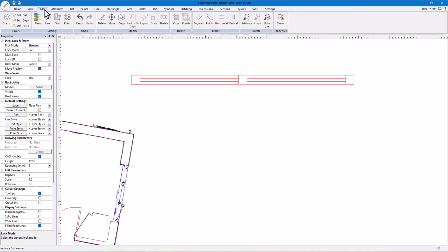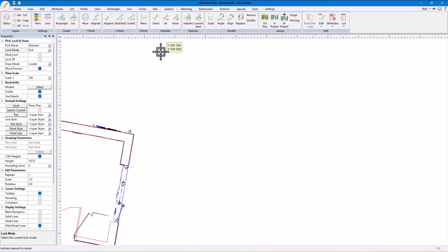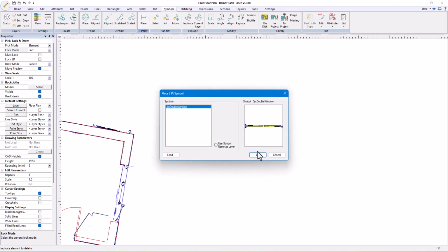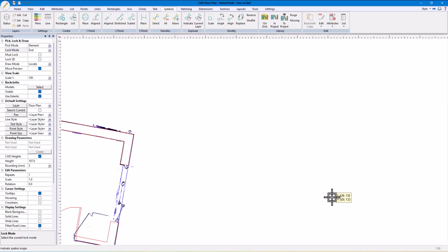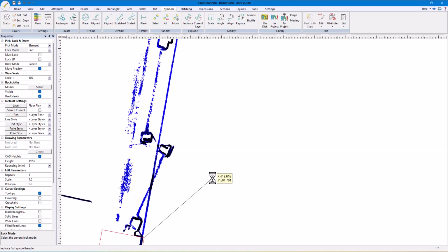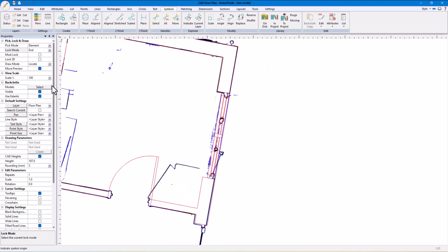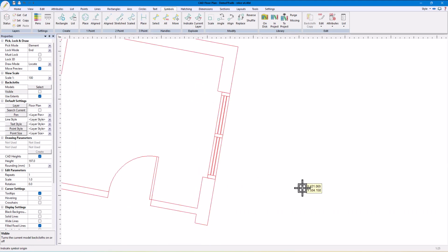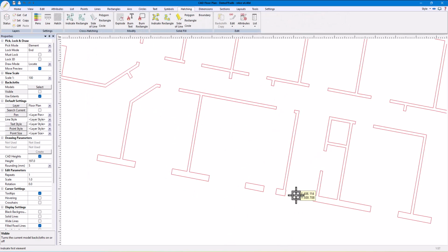Now we can delete the symbol and try to reinsert it using the 3-point option to test it. That seems to work fine, so we can fit it into an appropriate opening. Note, the end lock mode has no effect if there is nothing suitable to lock to. Using nothing but the tools we have just been exploring, the rest of the walls can be completed with ease.